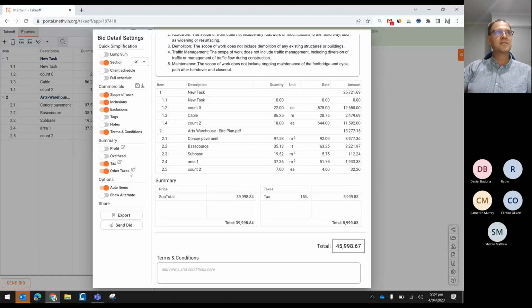They've got other taxes where they have to declare how much materials and labor they've got, and they pay around 7.25% on their labor and materials. So we've got a feature here. If in your resource table you've set that up correctly, you can then filter out just your labor and materials and add that percentage on here, and it just adds under through here.